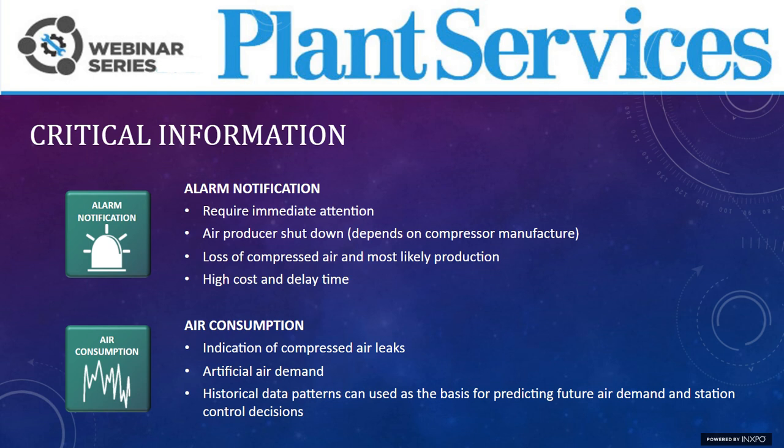Take a look at air consumption. Air consumption is another very important value, and it's not only because we can see the demand downstream. It also identifies leaks and artificial demands, future need for air producers, and also helps to improve a production process.